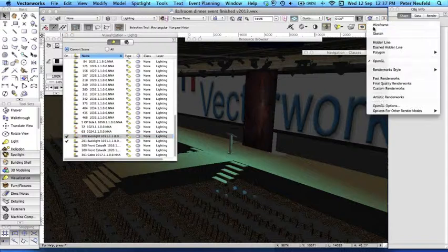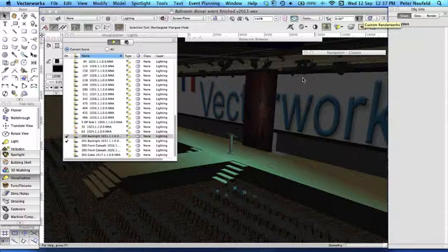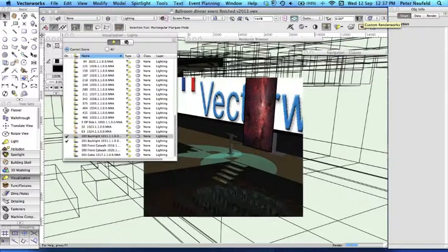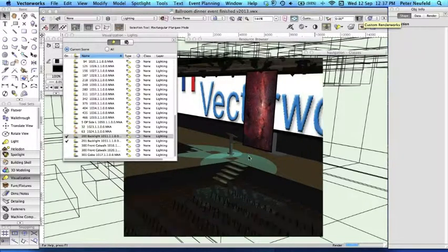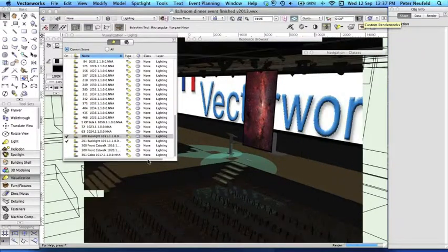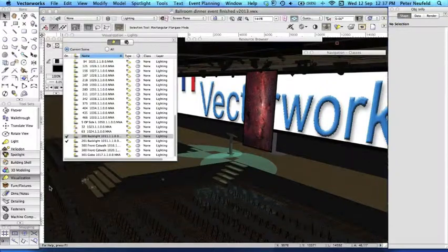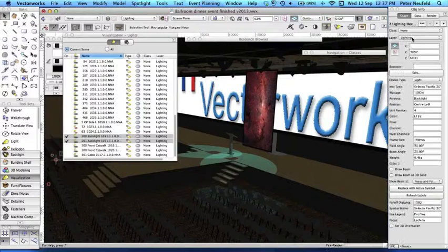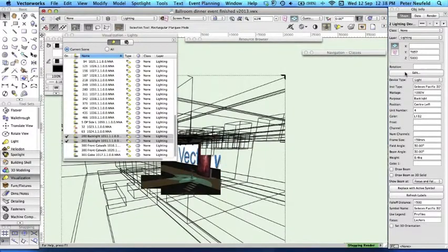Now I'm just going to go to a custom Renderworks render. This is to make things a bit quicker for the movie, and that's another topic, custom Renderworks. But you see here there's a sharp edge beam of light. These are 30-degree fixed beam instruments, and you can change the softness of that focus for Renderworks lights. I'm just going to hold the shift key down, select both of these, right click, select on document. I've got the two lighting devices here. I'll just stop it re-rendering.